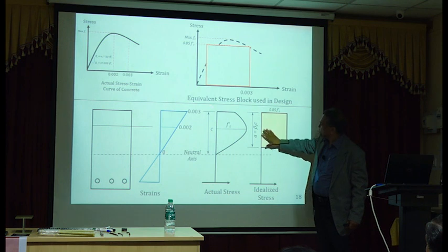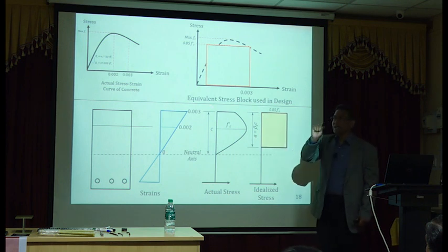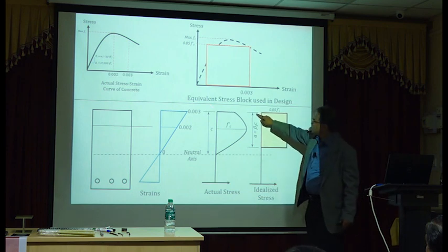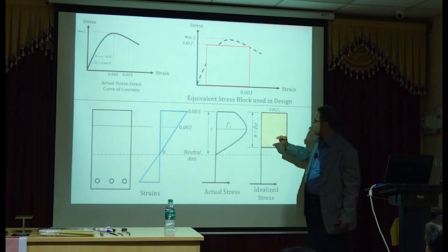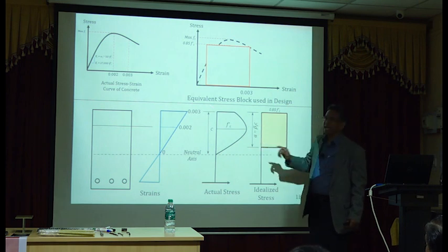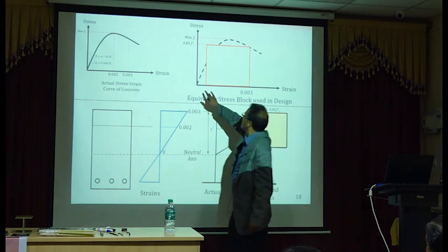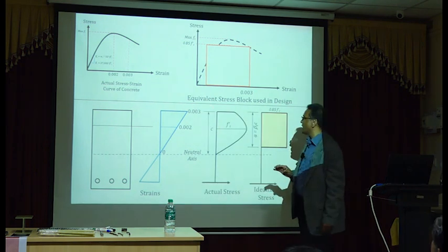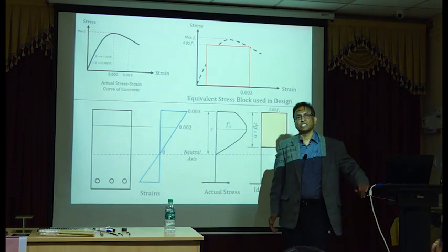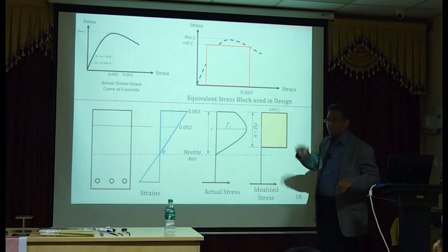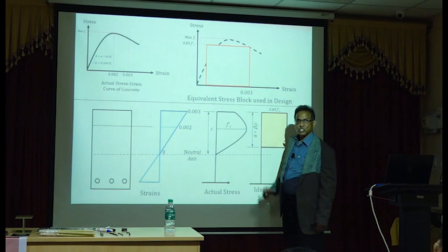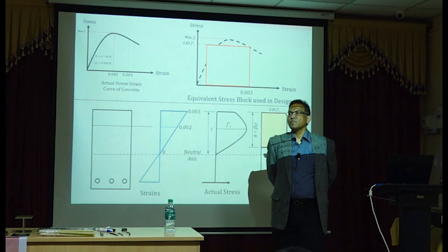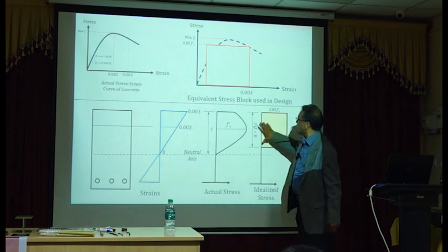This depth is the depth of the compression block, and it's known as lowercase a, which is small letter a, is what is used for this depth of the compression block. And that depth of the compression block varies. That means this depth to this depth, the ratio varies with f prime c. That means concrete strength. Okay? So smaller the concrete strength, larger the ratio. So 4000 psi concrete, which is about 27.5 MPa, for that, this is 0.85.